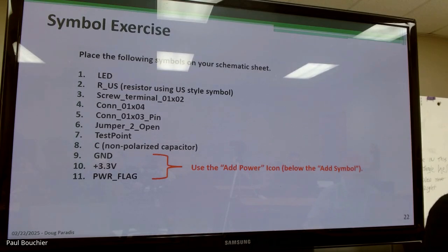Okay. One of the things I highly recommend when you're making connections: you can use DuPont style headers and pins, but they have a tendency to slip and fall off. So on new robots, not wanting to make my wiring more difficult, I am using the same pitch, which is 2.54, which is the JST XH series parts.